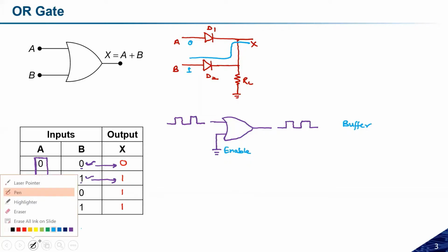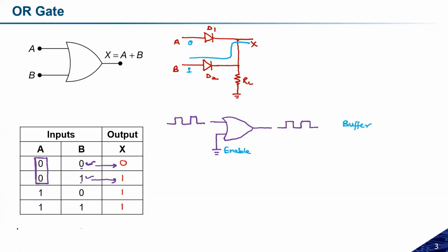Now let us talk about the second case. What is the second case? Suppose I have an OR gate. If we check the second case, if I'm providing logic 1, or fixing logic 1, to any of the inputs, whatever input I provide does not matter, I will always get logic high.